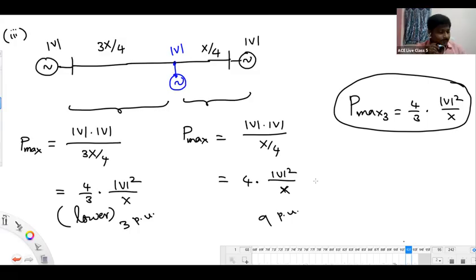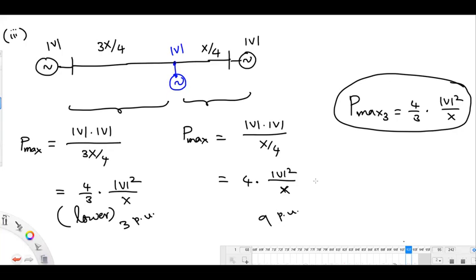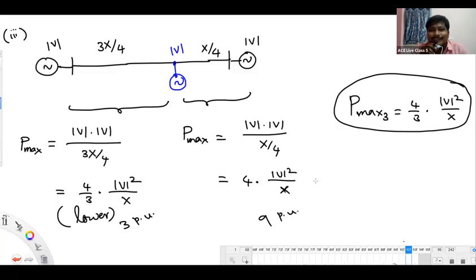Any other doubt, Surya? Sir, another general doubt in fault analysis. Tell me. If we have a star ungrounded system, in an LG fault the fault current value is 0, right? Yes, fault current value is 0. Sir, by the concept of network I understand, but by physical significance I can't get it. No current flows, Suryan. You don't have a closed path for current flow, right?